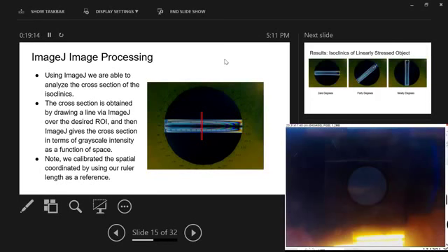We took full field intensity measurements of our polariscope plane, including the ruler, for angles of the ruler at 10 degree increments through a whole 90 degrees. So you can see that our ruler as oriented right now is at what we would call 0 degrees.